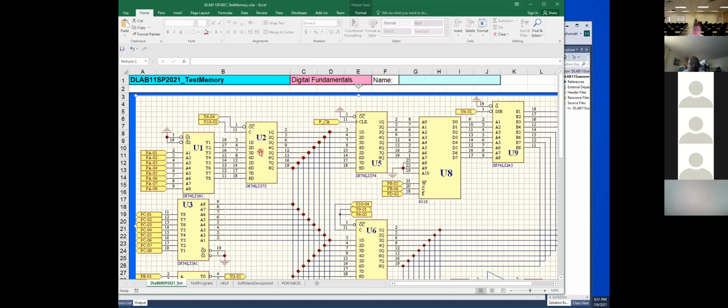That doesn't matter. But the thing is, you can set pin 1 of U2 to be 0 while you latch. They automatically come up. Right, I know that's fine, but when you write to port B, it also controls the U6 at the same time, and you don't want U6 to go through when you write the address. Right. So the thing is, therefore, what we want, I want to separate it. I want you to latch first.